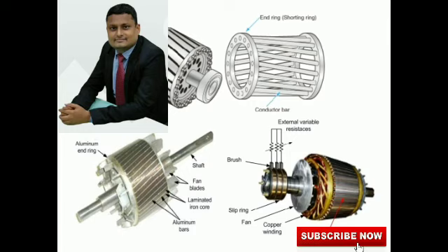Now cross section of the end ring: higher delta than the stator is allowed. So we have already learnt that AC equals IE upon delta E. You have to choose a suitable depth and thickness of the end ring. That will be rectangular.